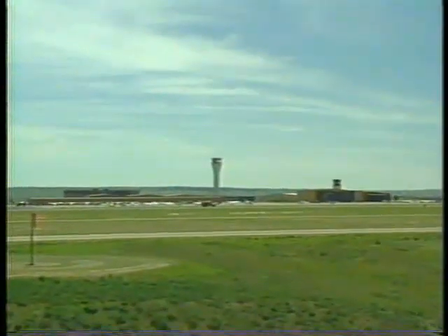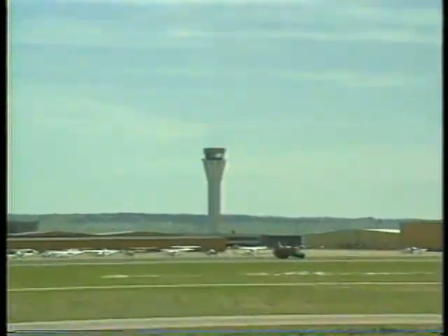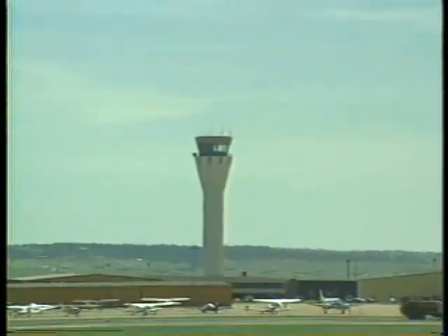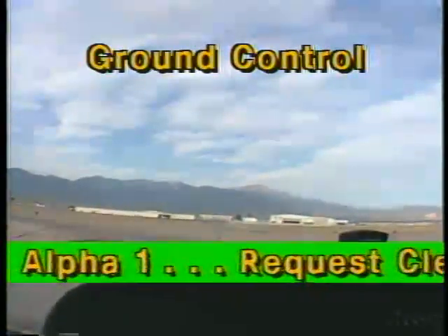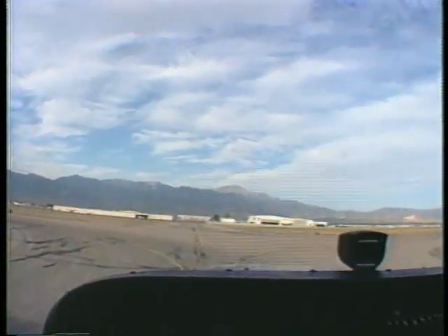At airports with an operating control tower, you must obtain a clearance to land. "Cessna 740, cleared to land, runway 17." You may also receive additional instructions after landing. "Cessna 740, next available taxiway, contact ground, point 7." "Cessna 740, roger. Jensen ground, Cessna 62740, clear of 17 at Alpha 1, request clearance to general aviation ramp." "Cessna 740, taxi to general aviation ramp via Alpha."